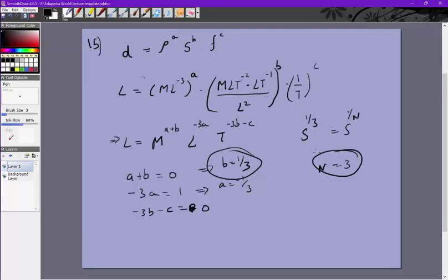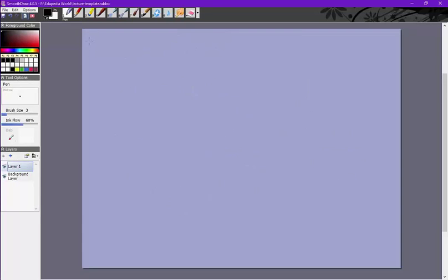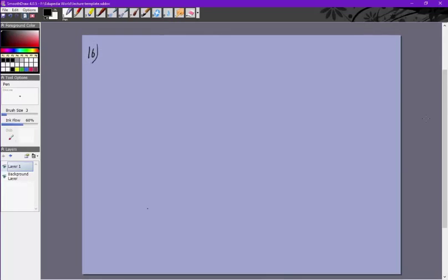Let's move on to question 16. We are given that a galvanometer gives a full scale deflection with a current, let's call it I_G, of 0.006 ampere. When you connect it to a resistance of 4990 ohm, it is a voltmeter in the range 0 to 30 volts.